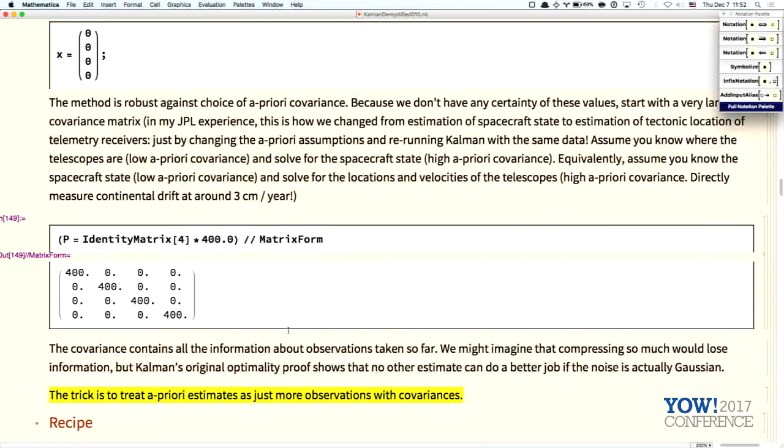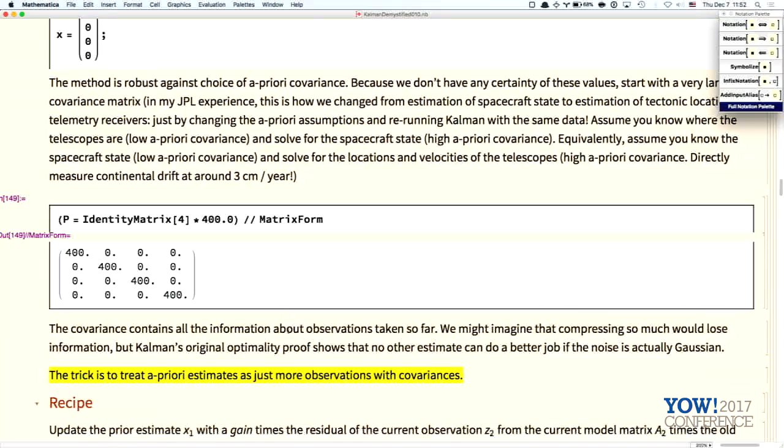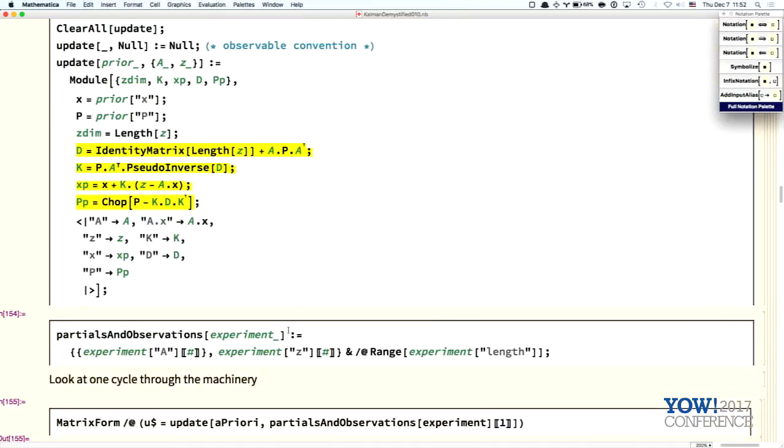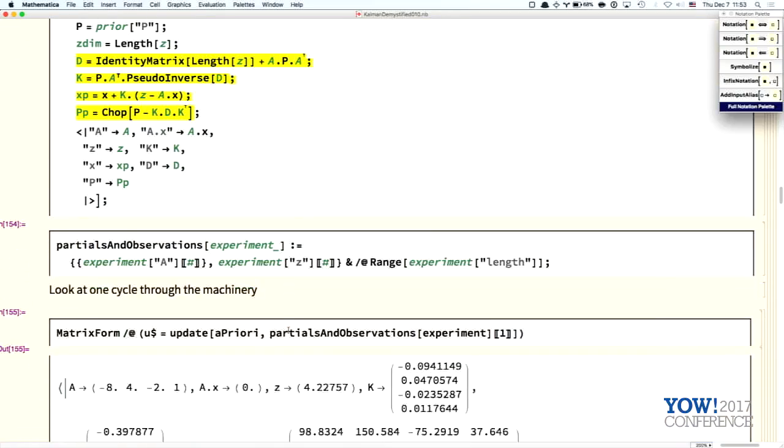So now we're going to do this incrementally. I'm going to run my data through the Kalman filter. I do not know the coefficients, so I begin with zeros. Another way of expressing that I don't know them is the covariance matrix. I put in an expression of my uncertainty in those zeros, and I put it very large, 400 along the diagonal. I don't know anything. I picked 400 because it makes the plots look nice.